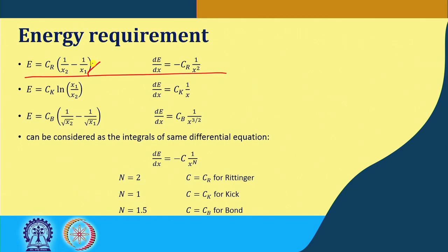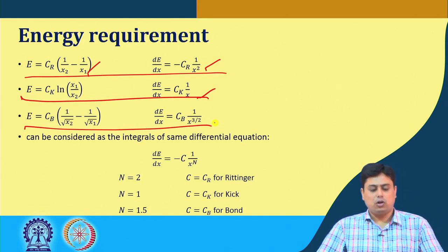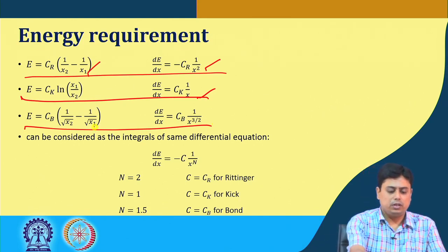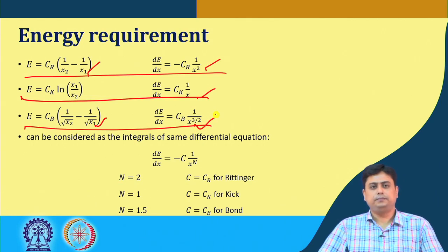First is the integral form, the second one is the differential form. Similarly, in the second row we have Kick's law, integral form and differential form, and the third one is Bond's law, which has an integral expression of this kind and a differential expression of this kind.